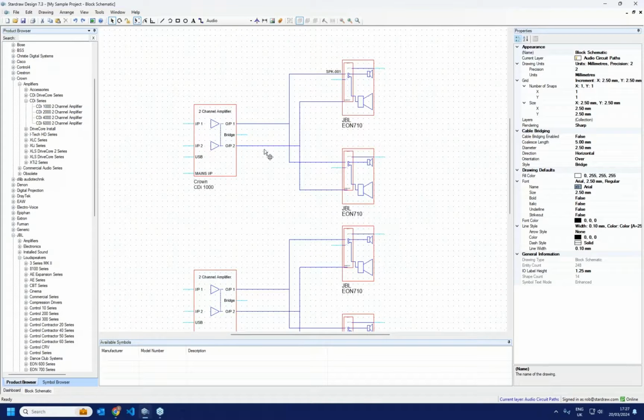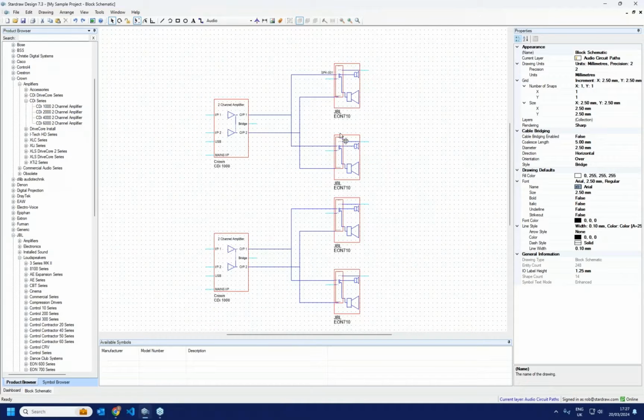So this is all extremely good, but I don't really want to have to type in every single label on every cable across my whole system. So instead, I'm going to use this tool. It's called the Cable Labels tool, and this allows me to set all 3 cable label values in a single action. It pops up a modeless dialog, so I can set some values. So we'll say the middle label is AWG16, end label can be Audio 001.